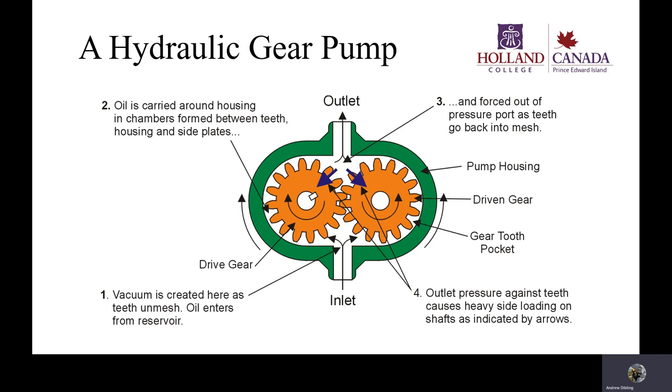So the reservoir for the hydraulic fluid, while at rest, is experiencing atmospheric pressure. It's not until the outlet of the pump gets in motion and hits that first restriction that any pressure is built.